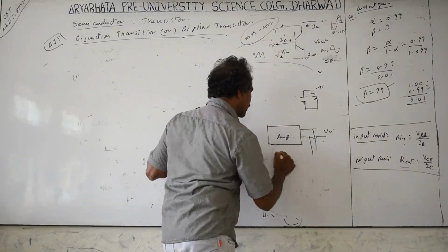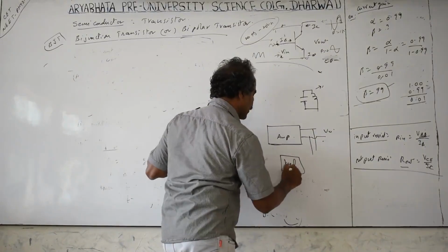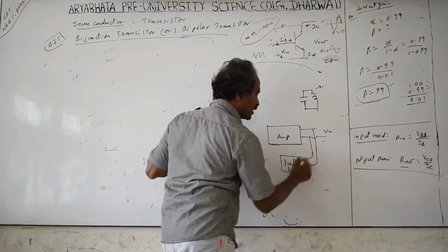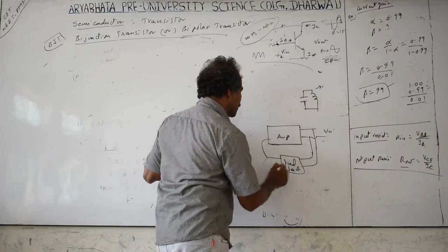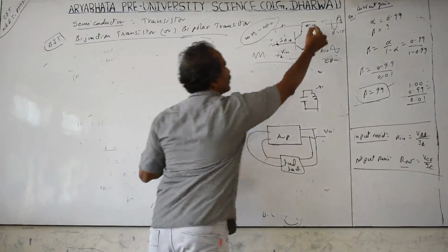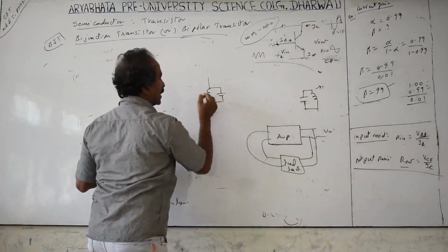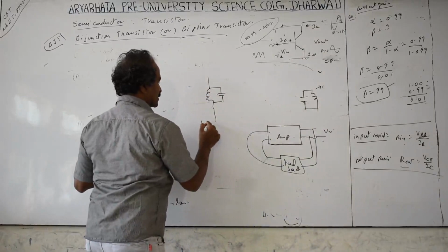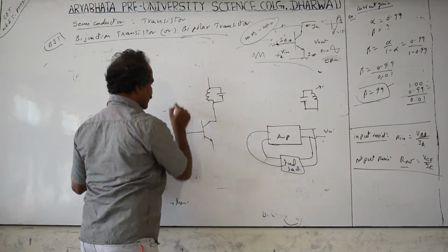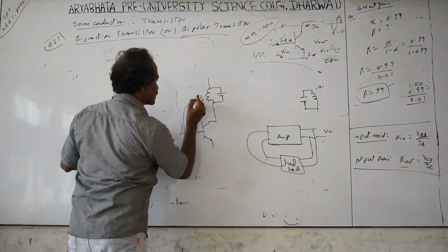transistor circuit diagram for the oscillator circuit they will mention. Oscillators. As the signal is given, the oscillator's purpose, we have the LC oscillator circuit. In the LC oscillator circuits, we are using inductance and capacitance. If you charge the capacitor first and connect it across the inductor, the charges try to discharge through the inductor, but the inductor, by back EMF, sends the charges backwards.